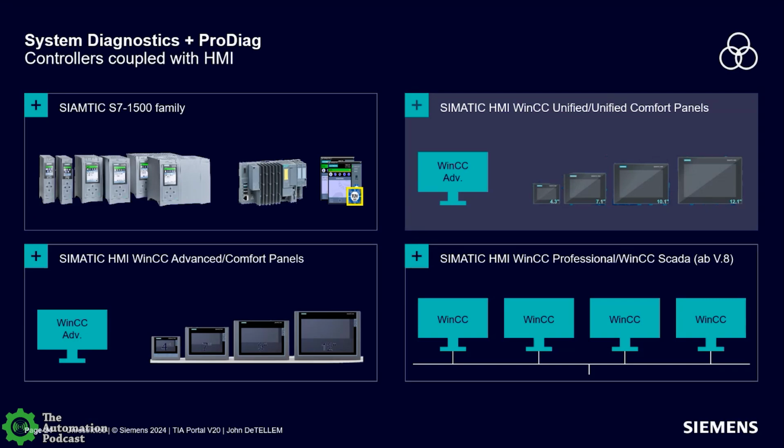Now, you and I have talked about the integrated system diagnostics in TIA and the ability to set up process diagnostics. That's fundamentally our controllers, our PLCs, integrated and connecting with diagnostics from the hardware to the process and the PLC up into displaying that on the HMI. And on the HMI, it can be displayed as an alarm text in alarm windows. It can be described in a control that represents the architecture that's defined in the controller, or a control that represents the actual ladder logic or the code that's problematic in the PLC with the process diagnostics.